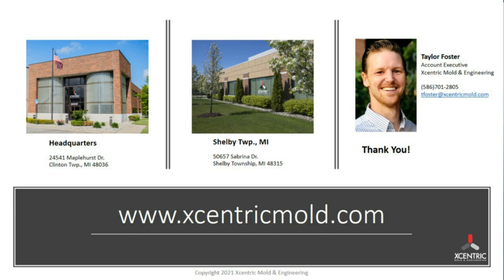At that beginning phase, obviously you're doing 3D printing on almost all the parts, not the CNC one that's metal, but the other ones. You're doing that early 3D printing verification. And then if those parts are going to move to tooling in the end, yes, as early as possible, once you've got that 3D printing side of things nailed down, go ahead and start verifying with that prototype tooling. Because as you found, CNC lead times are 5-7 days, 3D printing lead times 3 to 5 days, something like that, typically speaking across the industry.